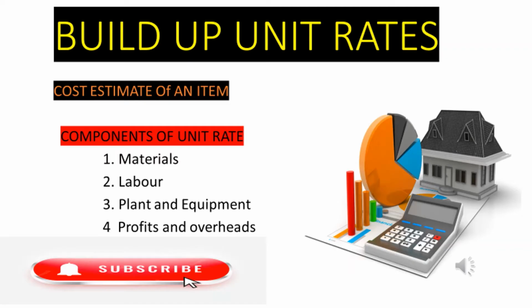We are still building up unit rates. We did a unit rate on tiles. Now we want also to do another unit rate. We estimate the costs of an item, that is terrazzo pavings. So the components of a unit rate are material, labor, equipment and plant, and then we have profits and overheads.